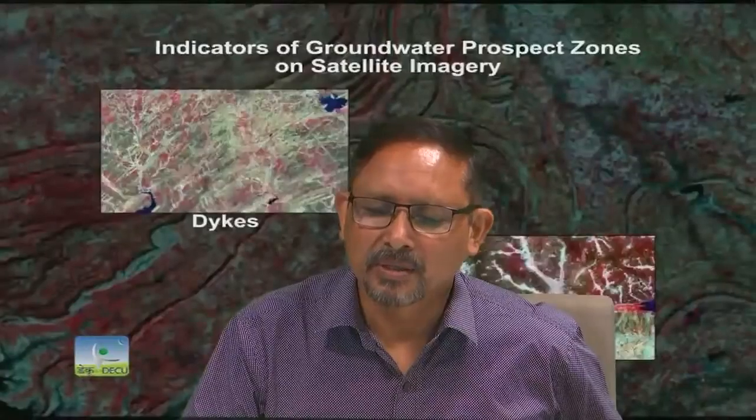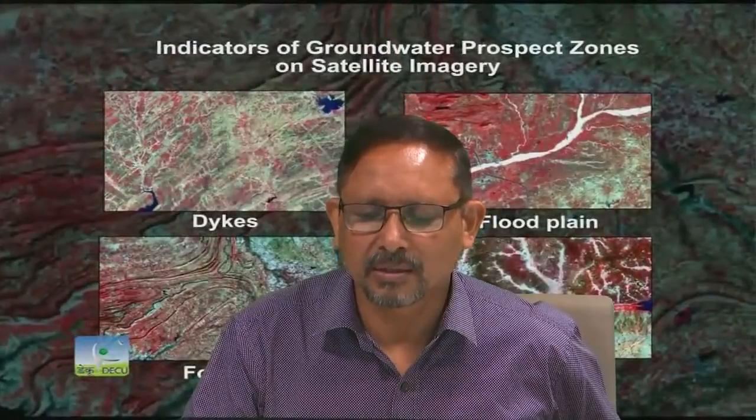Can you show how we can prepare a catchment with these softwares? You can do it with thresholding and extracting drainage patterns, and then defining the outlet. If you decide that here is the outlet where all the drains are coming and putting, you can generate its catchment area.